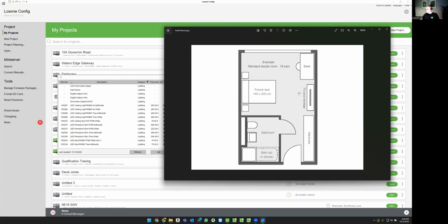I'd then put a spot here, so around where the TV area is, and also a spot outside the wardrobe and outside the bathroom. And ultimately that's as you come in the room. So you want it to be nice and bright. And then controlling these lights, I'm going to put a presence sensor, and because of the shape of the room, we want a presence sensor that's going to detect you as soon as you enter. So ultimately around the area of the door, and also put a presence sensor in the area of the bedroom.